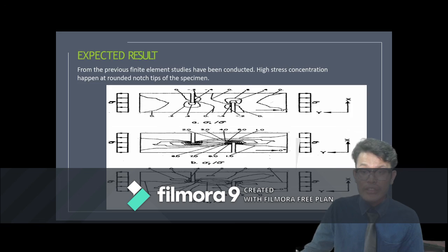The shear stress is 0.6 over a large portion of the shear part for the 0-degree specimen. At the notch tip, the stress concentration factor is 1.57. At the center of the specimen, a thin region of uniform shear stress equal to 0.6 indicates we can measure the shear strength by using this method.